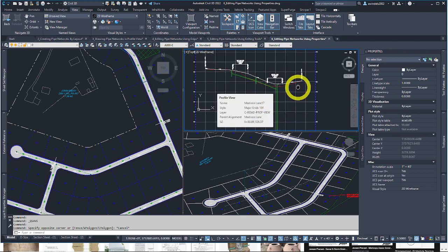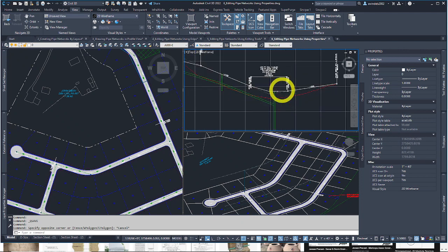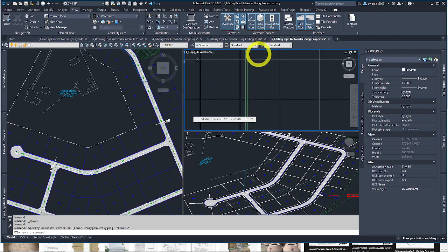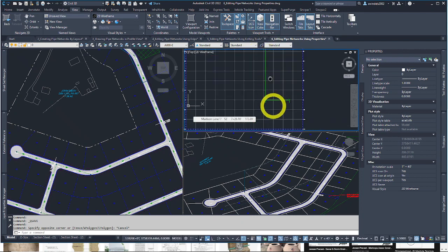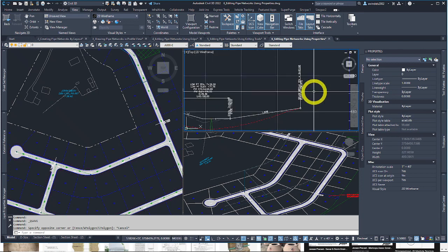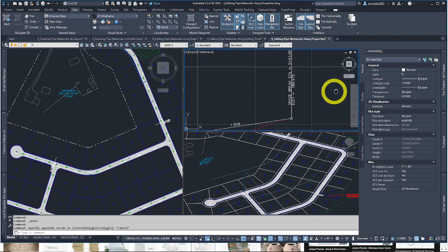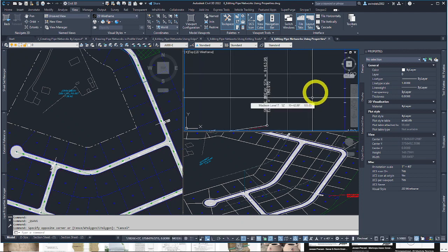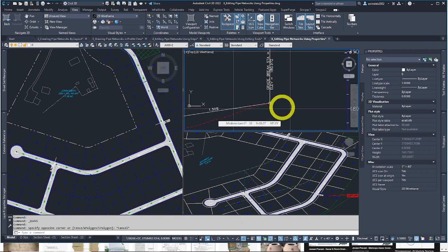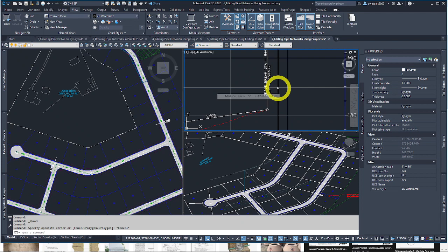And I go to this area here, and we're looking at the elevation of the manhole, and it's all over the place. It's really low. We're not in the proper spot. Furthermore, we're talking about this particular grade break label on the profile, and it says the elevation is 180.972. That's basically the elevation that corresponds to the center point of the cul-de-sac, which is also the location of the manhole. So this is the actual grade of the finished grade surface, elevation-wise. So keep that in mind.